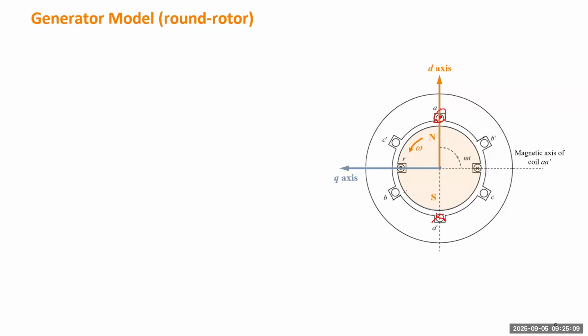It will generate a constant magnetic field, like a permanent magnet revolving inside. But because the relative angle changes along this circle in the cycle, if we want to determine the voltage induced only in winding A, we need to know how much flux is really coupled with winding A. That coupling will change periodically.